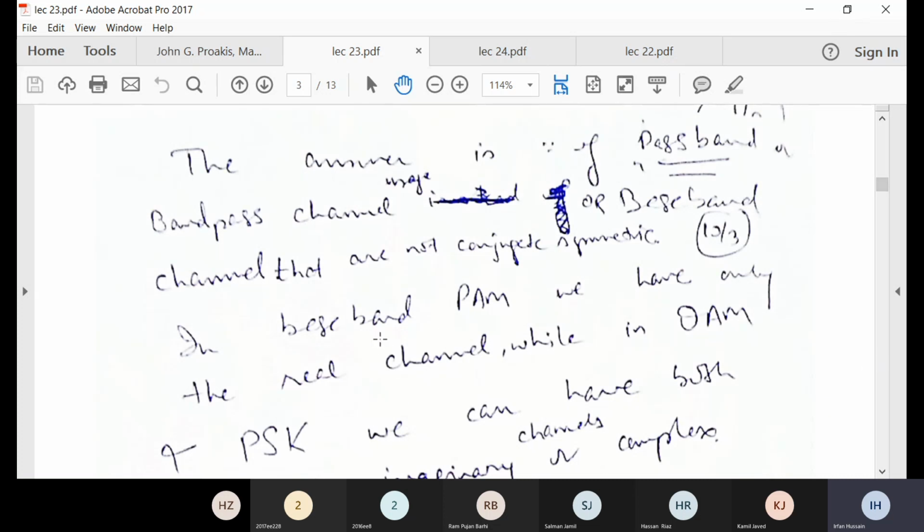Now let us go further. So we have baseband PAM, which I just showed you. Its vector diagram or constellation diagram is the same vector diagram that we saw for binary antipodal. It is just like that. You can also say it is PAM. For binary it is binary PAM, but you can add more symbols on the same x-axis, which could represent one orthogonal basis, or you could place another orthonormal basis, but that has to be one.